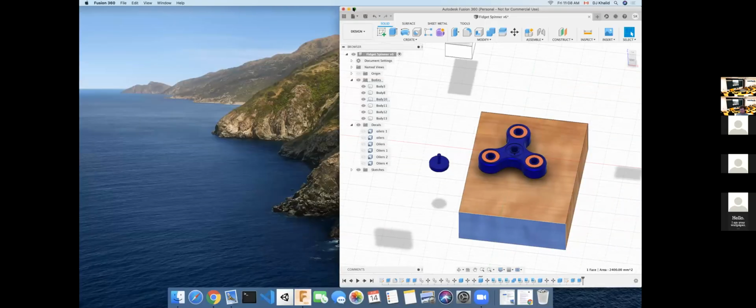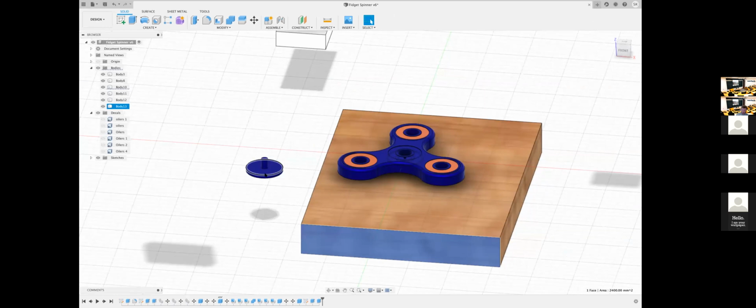We can't see you. I can tell from what I'm seeing that little stick here, the diameter is smaller than the hole, I think. So you need to make sure that the diameter of this hole is exactly the same, or if it's smaller so that it fits, make the difference very small, maybe 1/10 of a millimeter smaller, so that when you put it in here, it snugly fits, right? So it has to go like this.